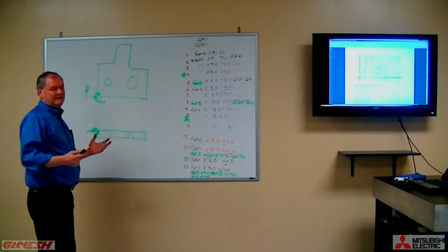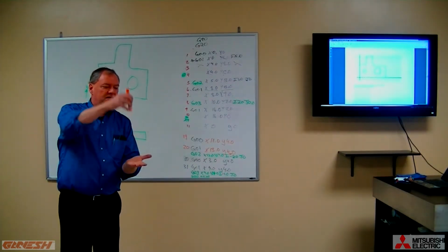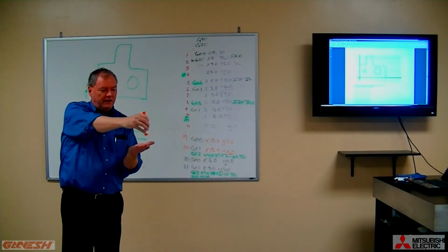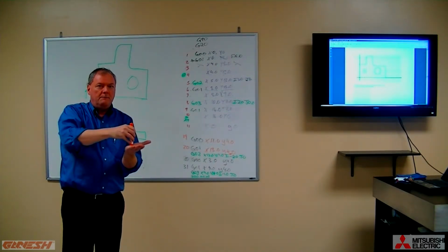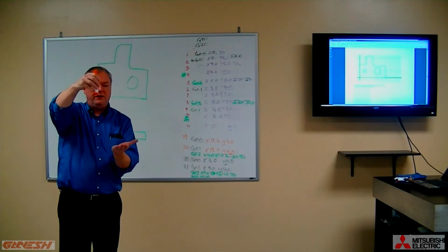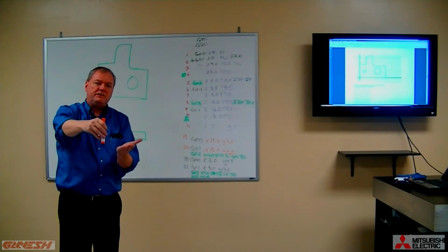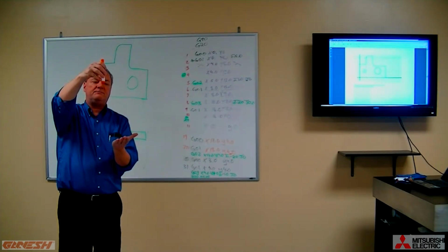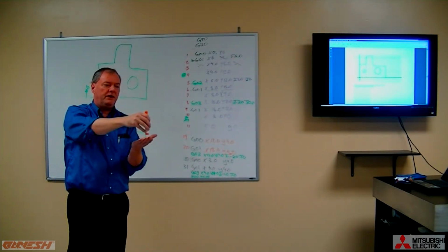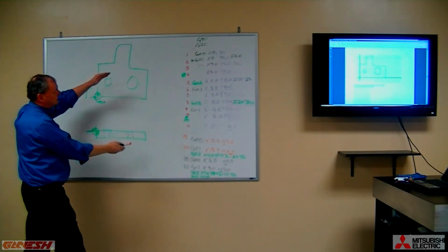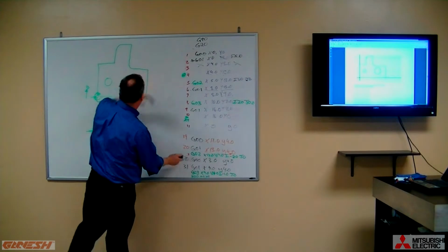So obviously that's not what we want. So we have to consider putting a z-axis down to a cutting depth, cutting a profile, picking that z-axis up, moving it to another location, dropping it down, machining a part, bringing the z-axis back up again, moving it over, bringing it down, and so on. So our x and y axis movements are all correct. There's nothing wrong with them.